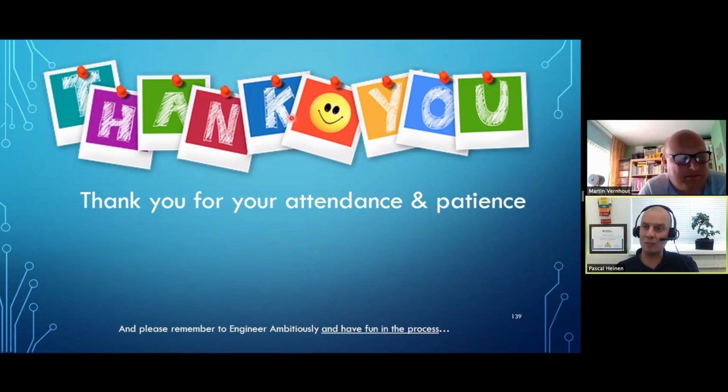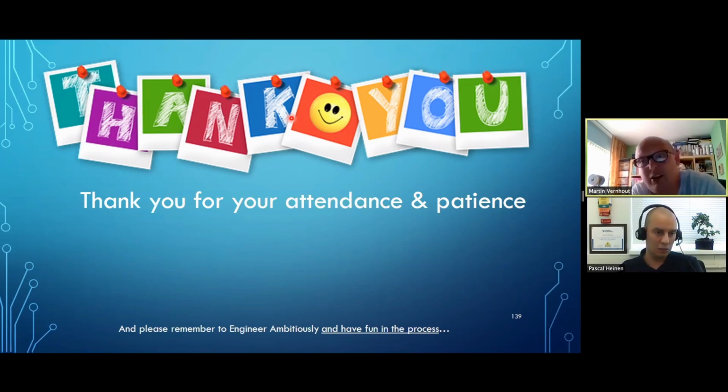We have one question from Femke. I think you already answered it in an earlier slide, but the question is, what are good resources to study for designing a multi-channel DAQ, data acquisition? I would first identify if you have a need for a multi-channel, non-simultaneously sampled signal, or is it simultaneously sampled? That's the first decision. Do they need to be at the same time, or can they be spaced a little bit apart in time? Because one solution is far cheaper than the other one. So multiplex is far cheaper than simultaneous.